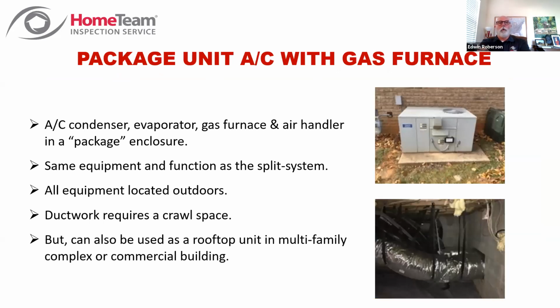Now, all of those systems we were talking about were split systems. You had equipment outdoors, and you had equipment indoors. And I know you're all familiar with package units, but you may or may not understand why they're called package units. The reason is all of the HVAC equipment is in that package. In this case, we're looking at a gas furnace. So your condenser, your evaporator, your gas furnace, and your air handler are all inside that package. Same equipment and function as a split system, but all of that equipment is located outdoors.